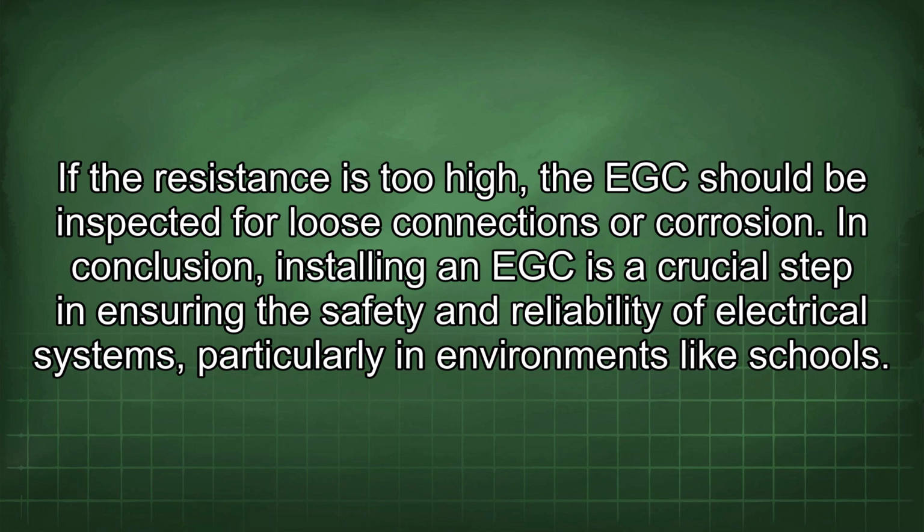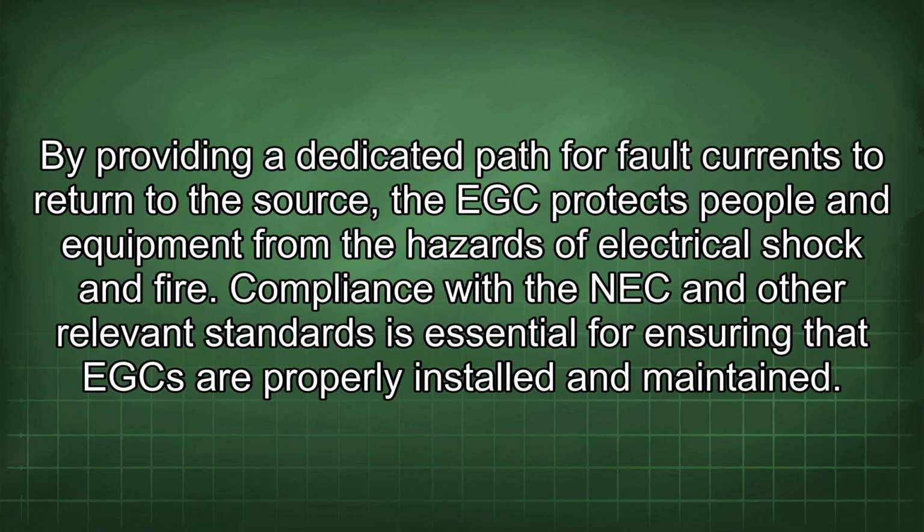In conclusion, installing an EGC is a crucial step in ensuring the safety and reliability of electrical systems, particularly in environments like schools. By providing a dedicated path for fault currents to return to the source, the EGC protects people and equipment from the hazards of electrical shock and fire.